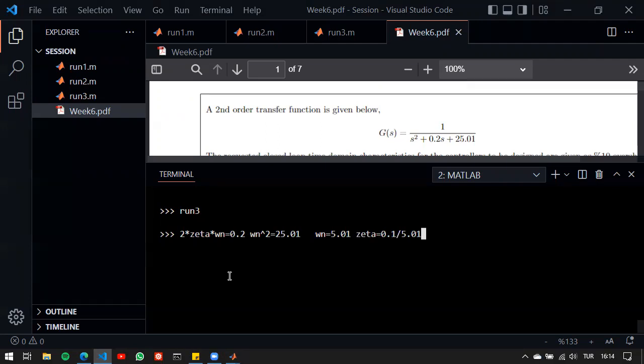That will become important, because if we have a low zeta value, I know that it will become sinusoidal in some case. And if I have high omega n values, I can also see that the frequency will be higher, because 2 pi times f is omega n. So this means that I might have something in the open loop that has a high frequency and a low friction or zeta value.